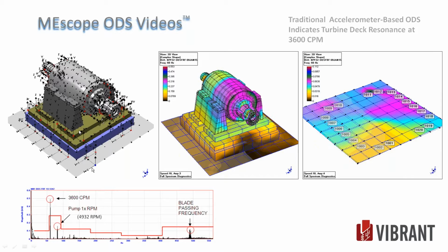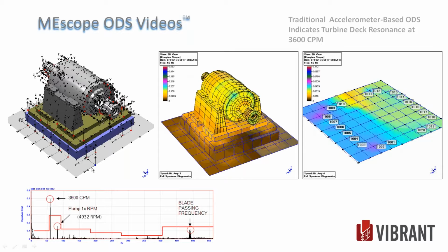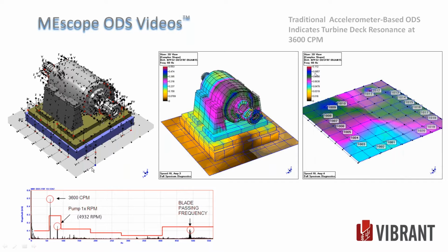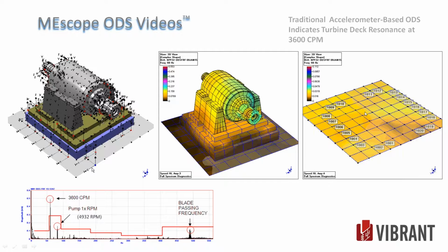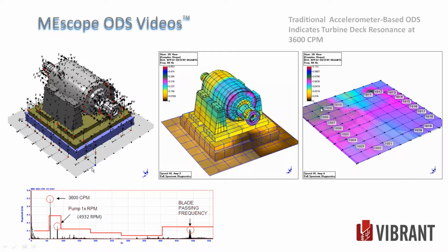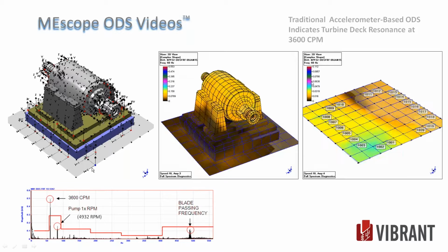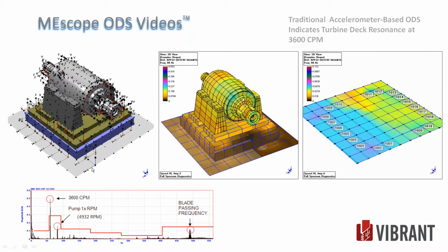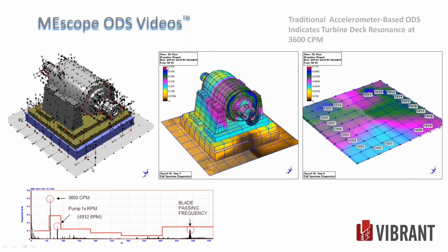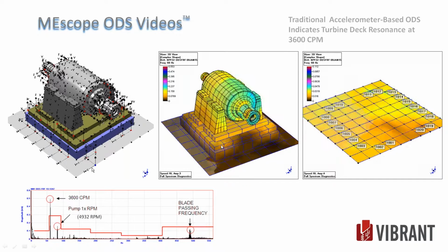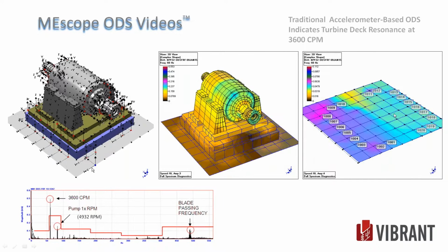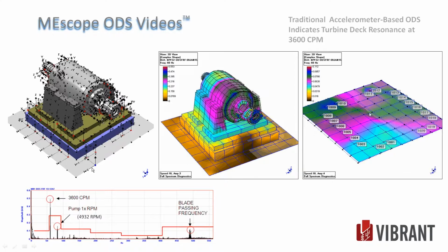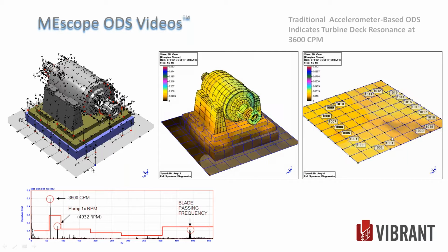A lot of those measurements were higher up on the structure. On the floor view over here, these measurements right on the deck, we got up to purple, green, blue. We got up to about 0.1 inches per second on the deck. So about twice as high as what you'd expect. The more higher up you go, like here, I was getting 0.5 inches per second on the boiler feed pump, horizontal. But on the floor, it's a vertical pitching motion across this apparent node line right here.